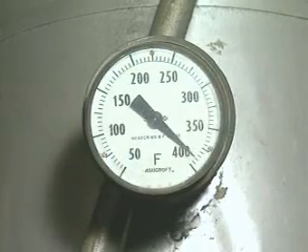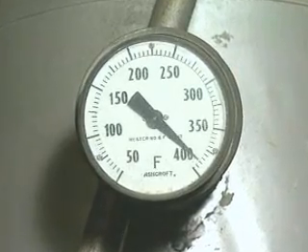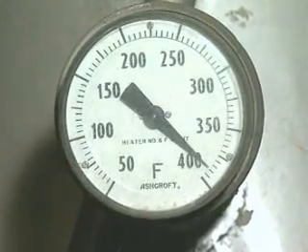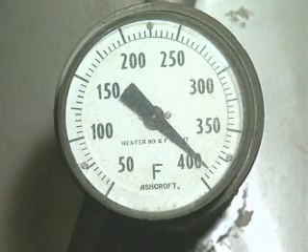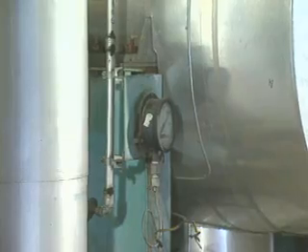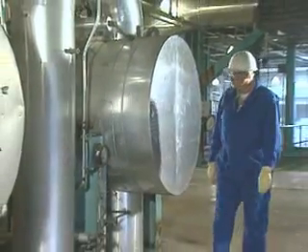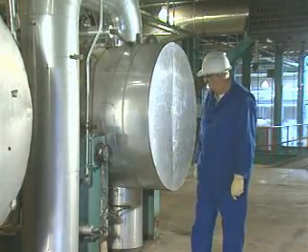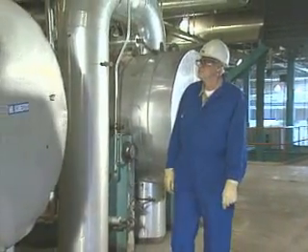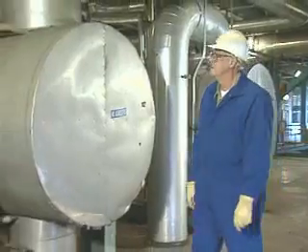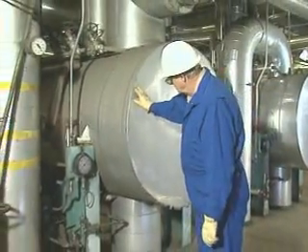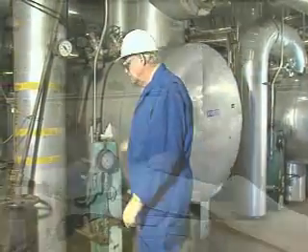To locate the heater that's not operating properly, you should generally start by checking the final feedwater outlet temperature to see if that value is within the normal range. Then work backwards, noting the heater outlet temperature for each heater in the train. If the difference between the actual reading and the expected one becomes greater with each heater, there's a malfunctioning heater upstream.